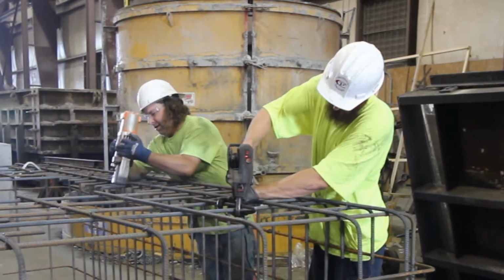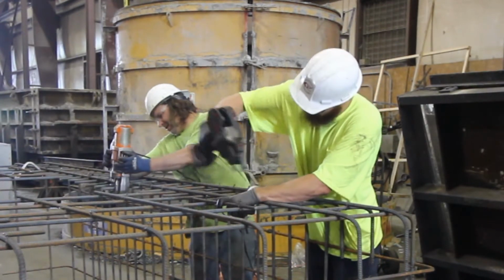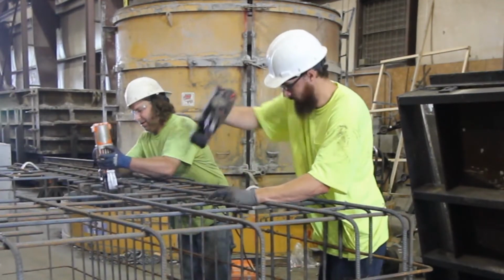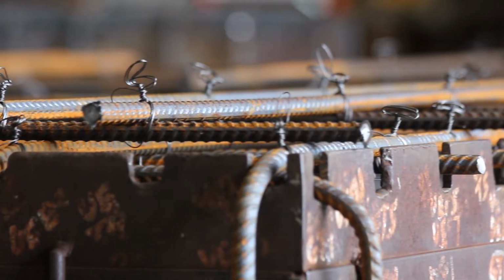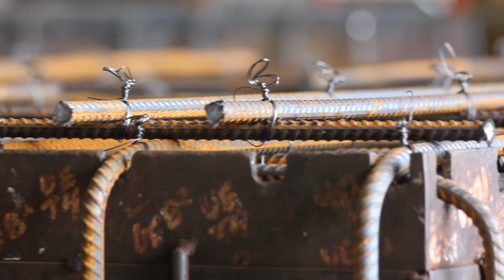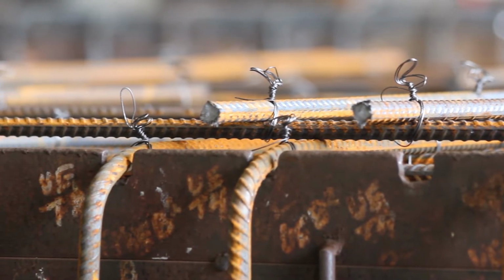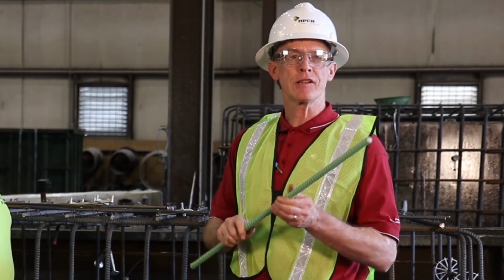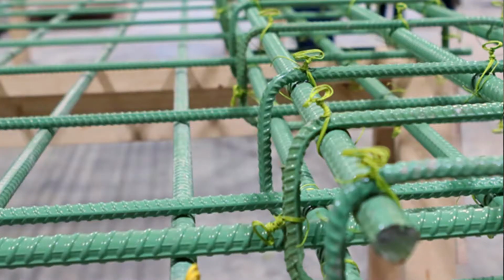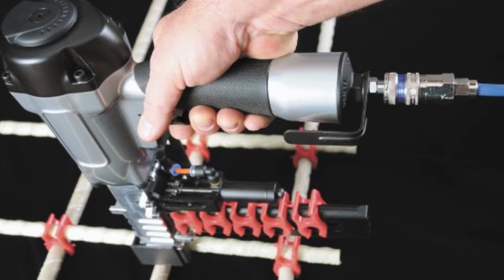Like spacers discussed earlier, the amount of wire ties used in spacing is up to the cage fabricator. It just needs to produce a rigid enough cage that keeps its shape when transported to the form, placement in the form, and the concrete pouring and consolidation. It's also very important when tying rebar, if you're using epoxy coated bar, that you also use coated wire ties so you do not damage the coating. In addition, commercially there are plastic clips that can make rigid cages and be applied using an applicator gun.